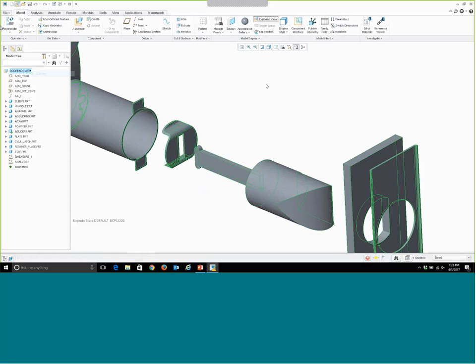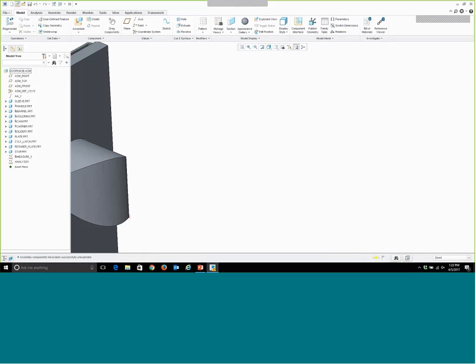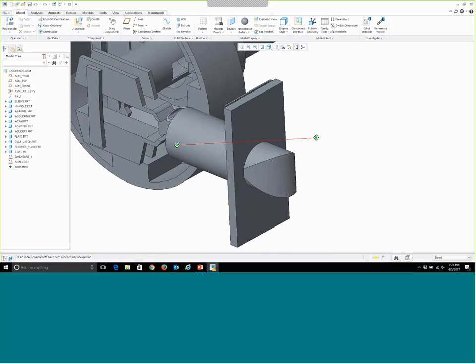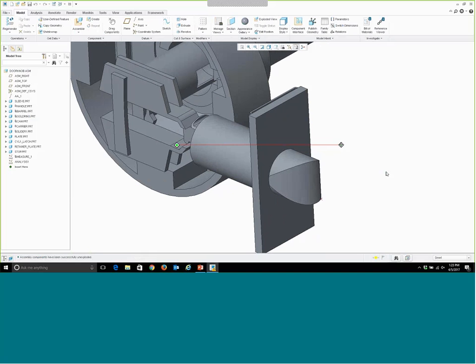Activate the assembly again. So the second piece of this, so that'll take care of giving us the correct spacing for that spring that we need. The second piece of this is to make sure that this slider actually goes into this plate and sort of tucks itself inside so that it doesn't get caught when you try to open the door.